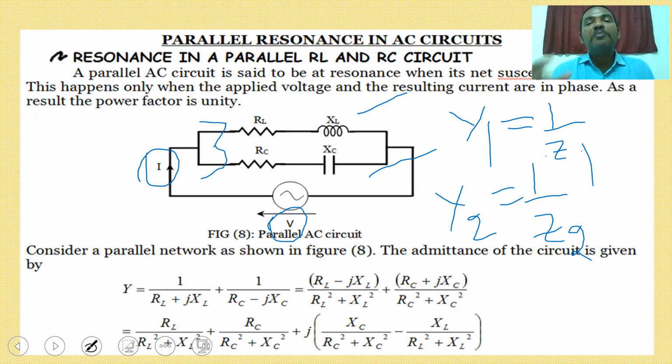The net imaginary part, or net susceptance value, is equal to 0. The total admittance must be equal to the total conductance value, so the power factor must be unity. The voltage drop across one branch and across the second branch is also the same. The currents are divided because two branches are connected in parallel with respect to the net current.